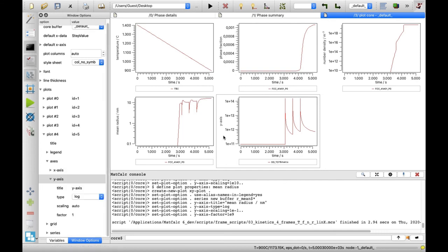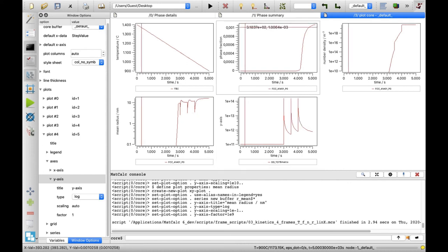Starting from the last plot, we can see the dislocation density curve showing 3 peaks. These correspond to the dislocation formation during the deformation segments present in the simulation. The dislocation density decreases after each deformation segment, due to the healing process. Looking at the phase fraction plot, the curve there does not seem to be influenced by the deformation, reaching the value over 0.001 and rising mainly after the introduced deformation.